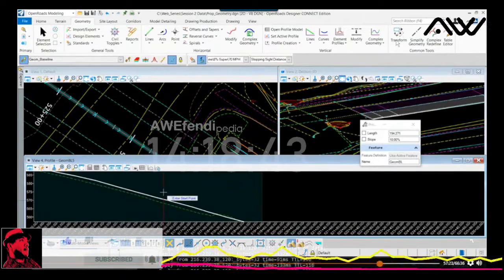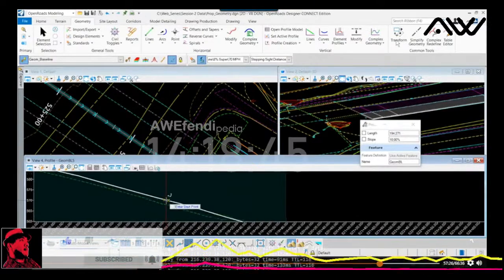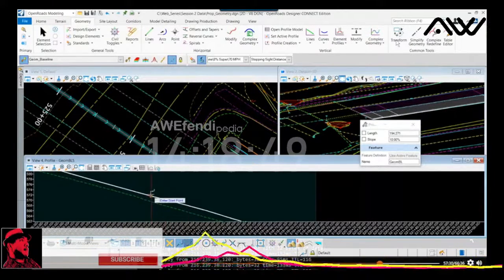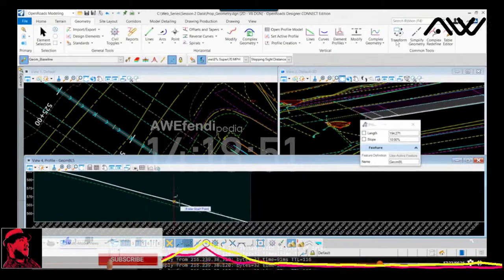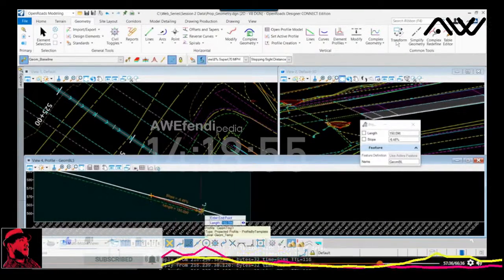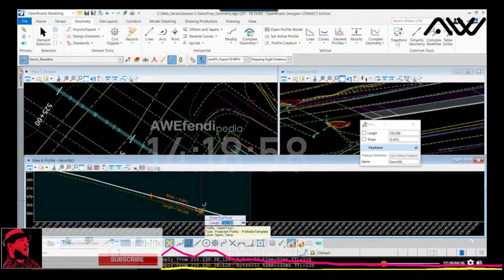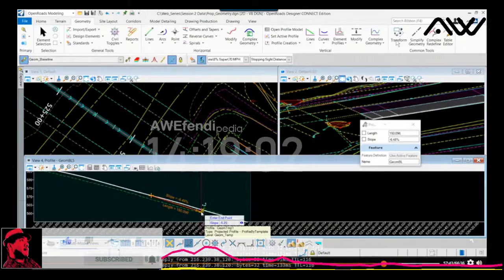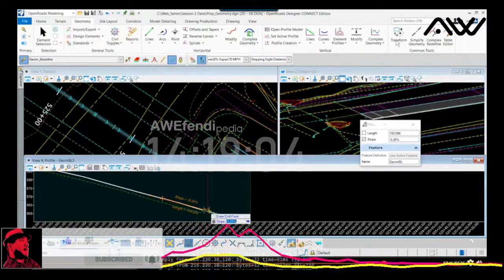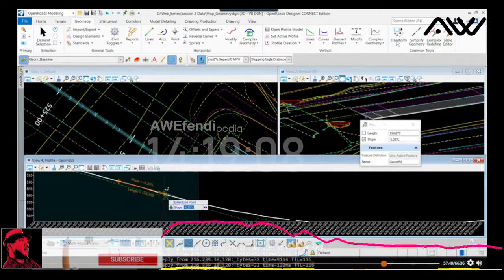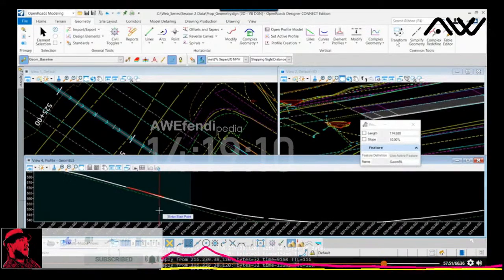And then I'm going to go down. I'm going to click and I'm going to follow along. Again, I'm just snapping so that I follow along this graphic, and I'm going to create the next tangent segment. Okay, the next tangent segment, as I draw it out, I'm pushing the right arrow, and let's hold to 5.25. And then we can just, again, sort of graphically input these values.